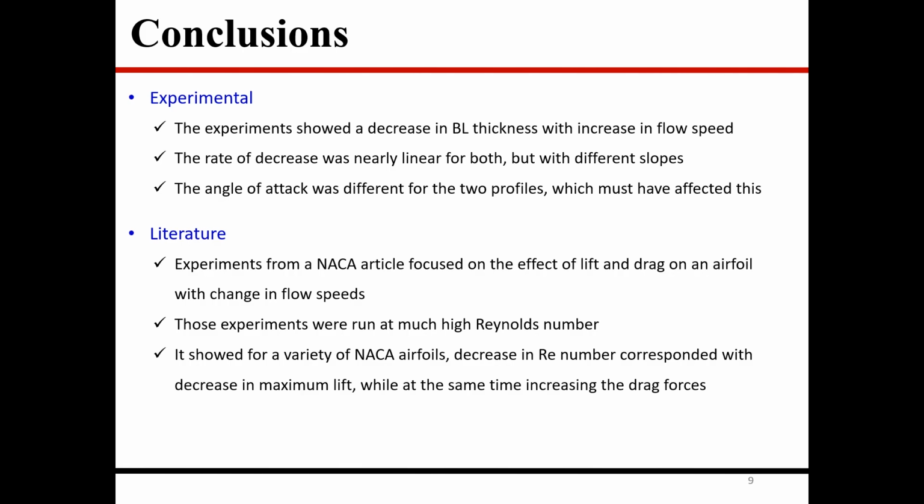While we have focused on the change in boundary layer thickness, we have found research articles that have focused on the change in lift and drag forces with change in Reynolds number, achieved by changing the flow velocity. Experiments from a NACA article focused on this aspect. They have shown that the decrease in Reynolds number has corresponded with a decrease in maximum lift while at the same time increasing the drag forces.